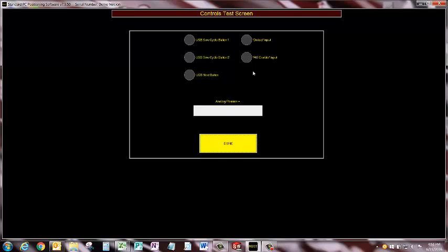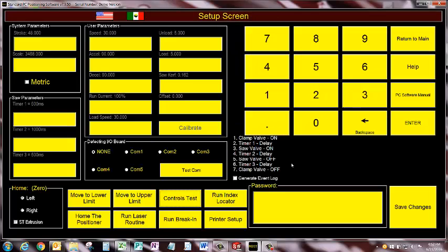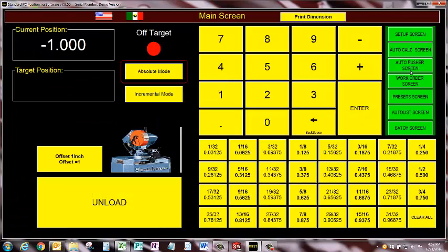This tells you that the M drive is getting the input, it is communicating it to the PC, and the PC software is changing the little pilot lights here next to the inputs. That's a very handy thing when you're trying to troubleshoot tool safe sensor or something like that.